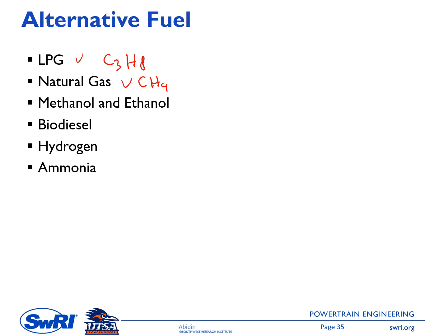Compared to gasoline, methane has better knock resistance because of its higher octane number. We will learn about this knocking and so on in chapter 9. However, natural gas has a lower heating value compared to the gasoline heating value.